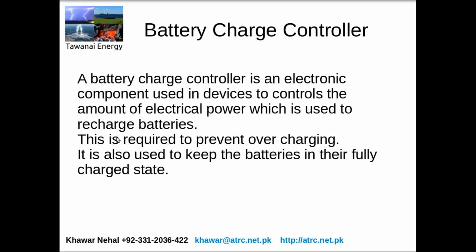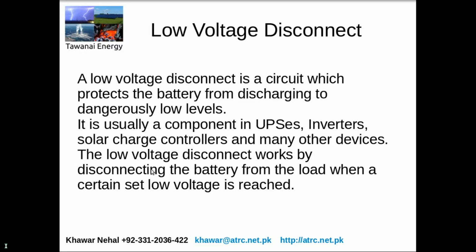The battery charge controller is required to make sure it doesn't overcharge, because after the battery is fully charged, there is no way the battery can stop the electric circuit by itself. So the battery charge controller will use voltage or temperature and other methods to estimate whether the battery is fully charged or not, and then it will stop the charging.